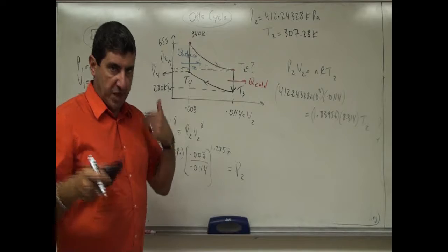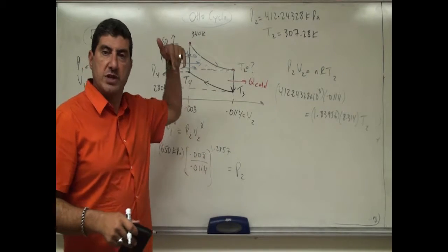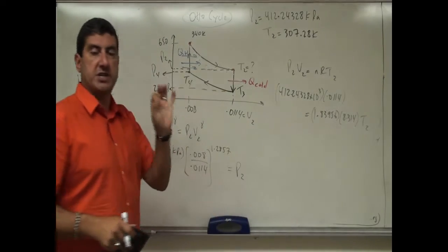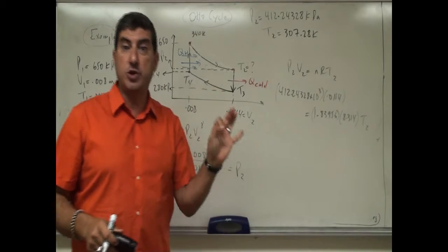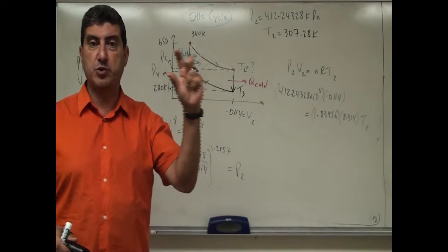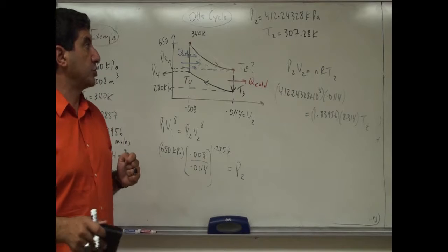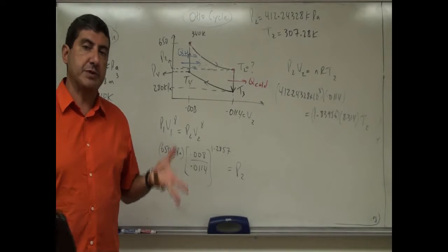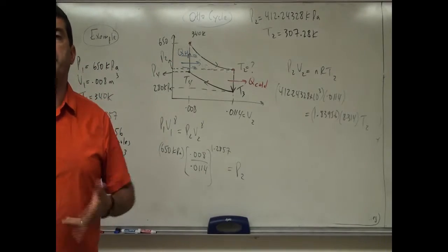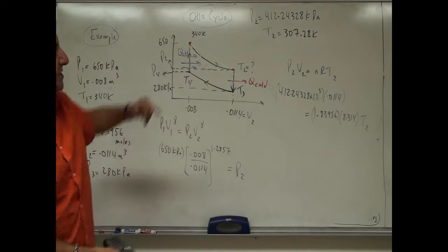So we noticed that the temperature drops quite a bit. In yesterday's experiment, the temperature didn't drop a lot. We did isothermal then adiabatic, right? And then we noticed that the temperature dropped to 320. The original temperature was 340 and then 320, and the temperature difference between the hot and cold reservoir was very little, right? So since the temperature difference between the hot and cold is very little, the efficiency of the engine ends up being very inefficient.